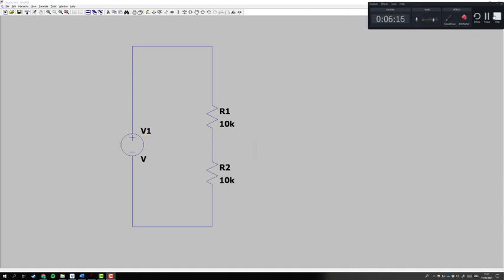So press escape from my demonstrator tool. Now, before we start a simulation, we should click on this voltage source, and we've got two choices. The first choice is to simply give it a value. Let's start with a flat value, a DC value of 1 volt.